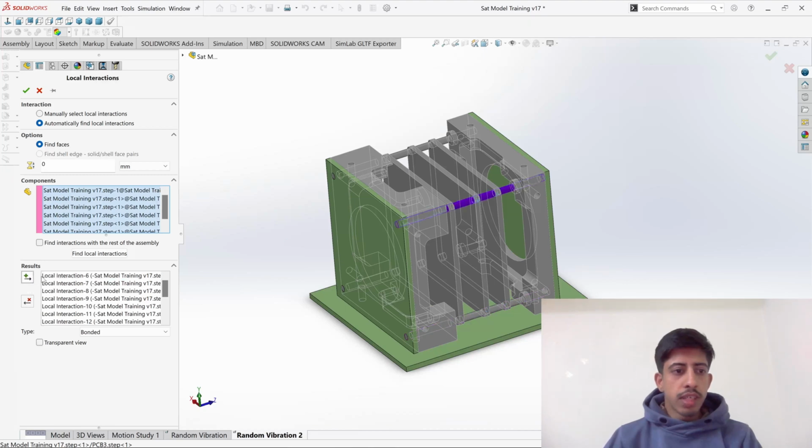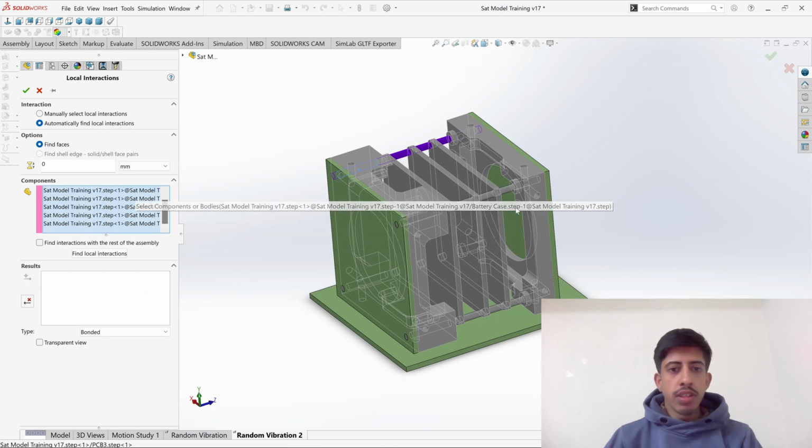So you can check if the interactions are correct, meaning if they are on the holes and the rod. But even if it is not so, you can just check and remove that connection. Add only the interactions that are correct. For now, it is only creating correct interactions. Okay. Now you need to deselect all the things.